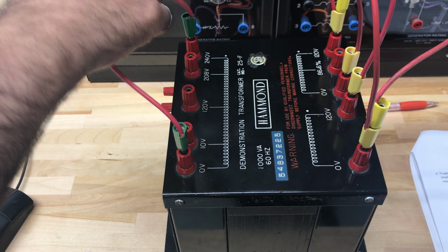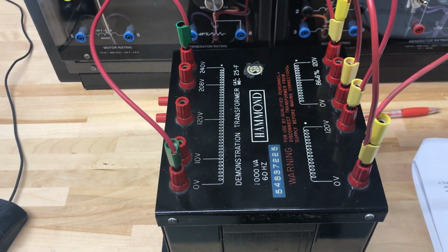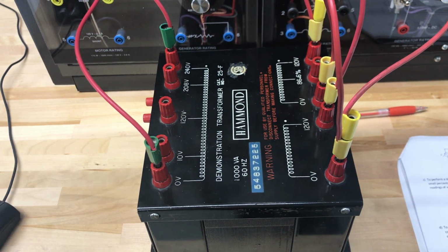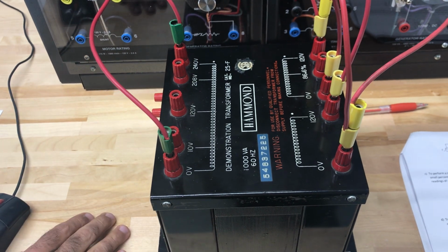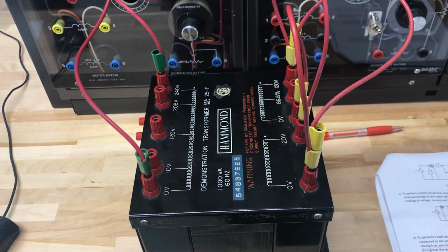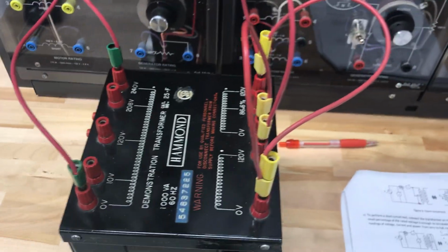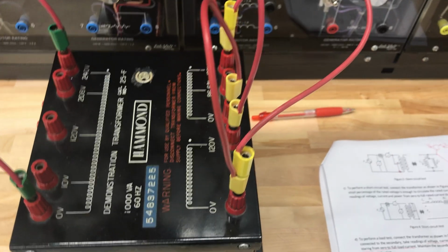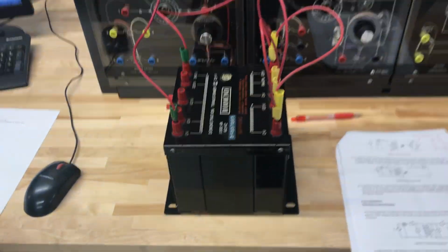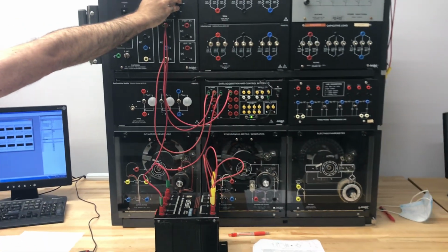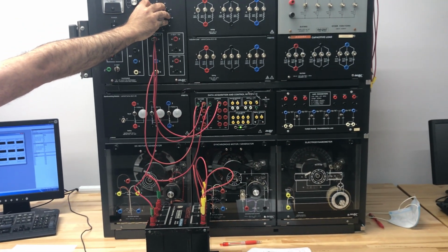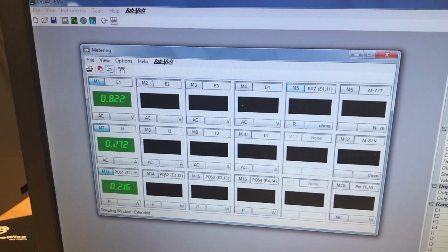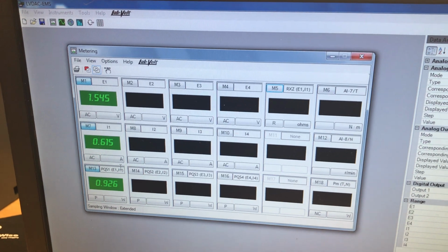The current here in the supply will not be more than 4, because the maximum current is 1000 divided by 240. It is 4 point something. I will keep only 4. Then I will start from the beginning again. So I will turn this on and I will start, but I have to be careful while I'm changing the voltage, because as you are seeing, the current is high.